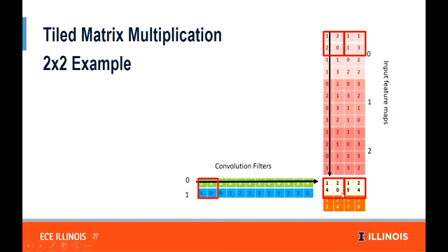Because remember, in this layout, essentially each row is one output feature map. So by doing this tiling, we are now generating multiple output feature map, same position elements, using the same input elements. So we are now beginning to exploit locality, reuse data in the input across different feature maps. Okay, does that make sense?